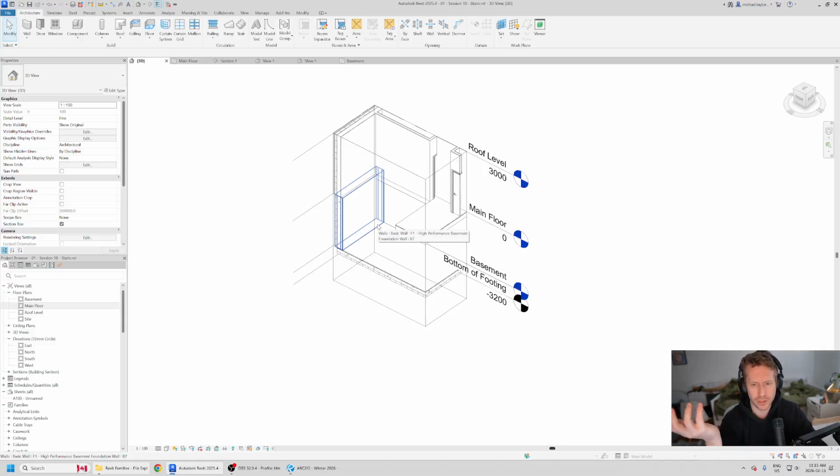Stairs are essentially made up of, well, for lack of a better word, the stair itself, the riser and tread. They're made up of a support on either side, and they're made up of a guard, and they're made up of a railing. So we can have all four things happening or not happening. You might have a stair where you don't want to show a support, but Revit still sees it as one of the elements as part of the stair family itself.